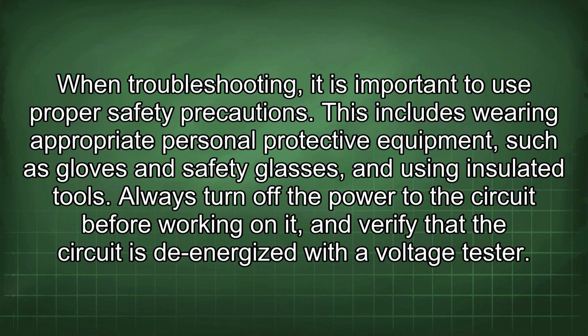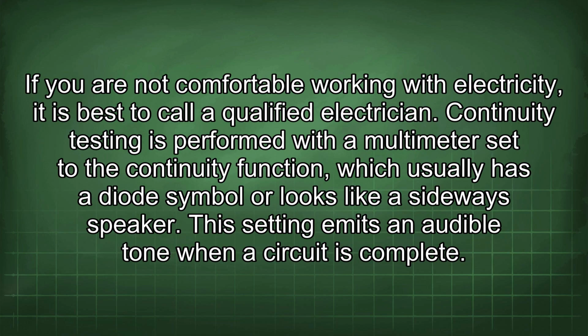This includes wearing appropriate personal protective equipment, such as gloves and safety glasses, and using insulated tools. Always turn off the power to the circuit before working on it, and verify that the circuit is de-energized with a voltage tester. If you are not comfortable working with electricity, it is best to call a qualified electrician.